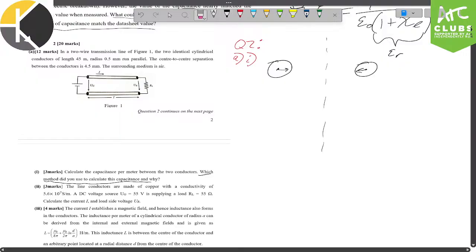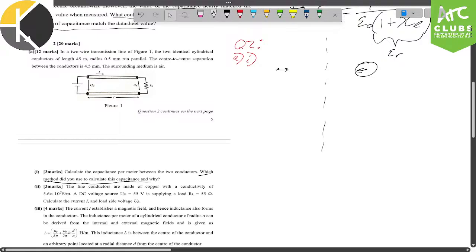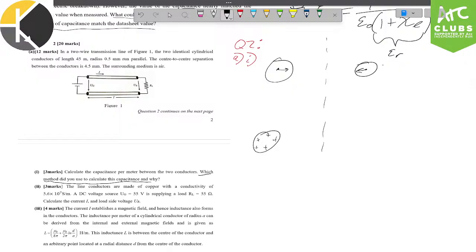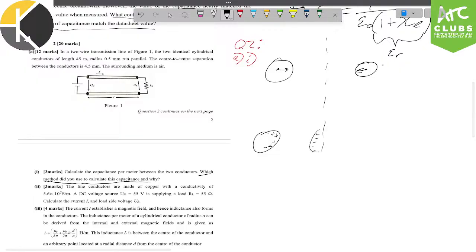However, something to note is because we have two conductive objects here, typically when we analyze just one cylinder, we assume that there is an equal dispersion of charge around the surface. This is one of our main assumptions for electrostatics. However, because we've added a second conductor, that's no longer the case. We have lumping of charges closer to the other one because there is some manner of attraction between the two.